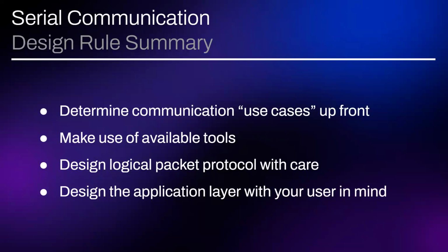Each sensor has its own address, so we'll send the command to the address, and then the command to talk back. The device coming back doesn't tell us how long that message is, so we have no way of knowing. We know the maximum length of the message, so we either receive it or wait, and then you time out.